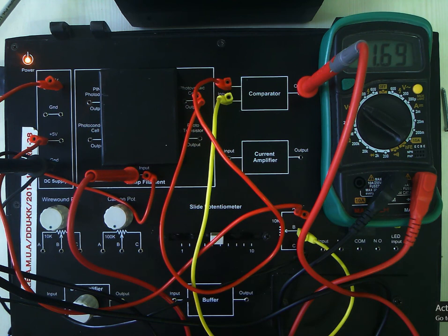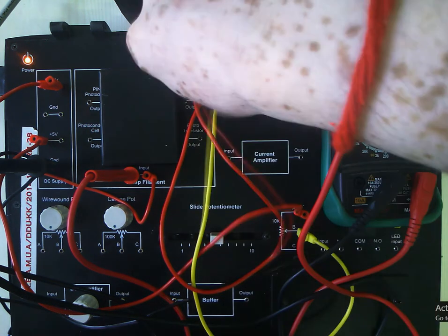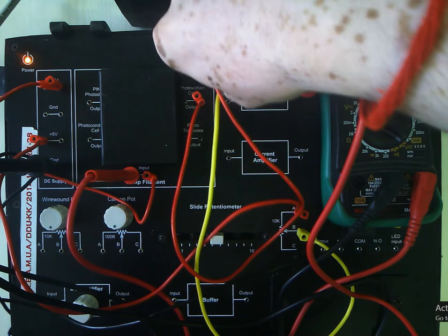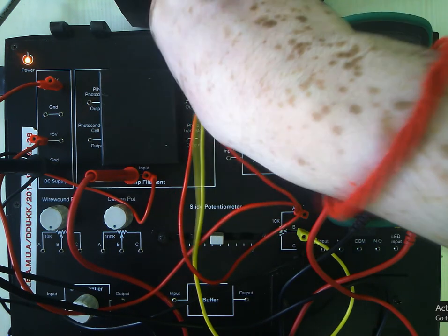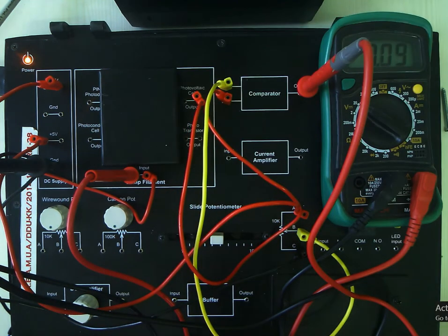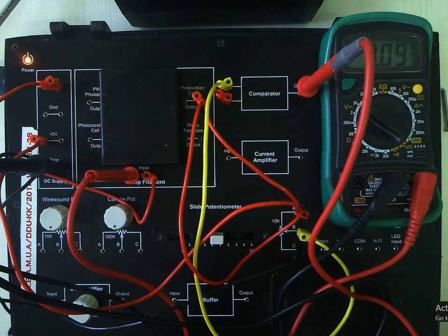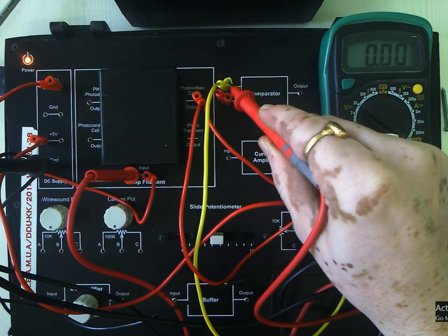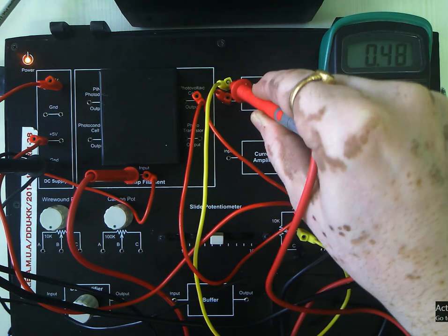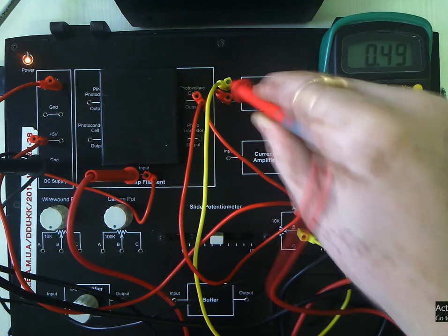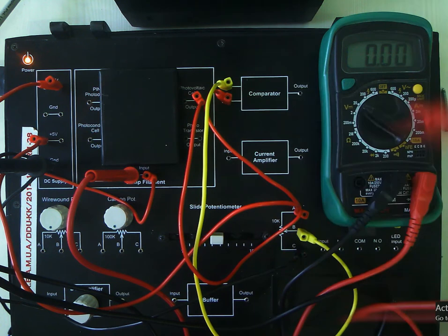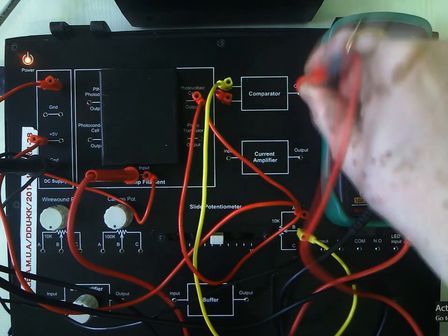Okay. What does that mean? That means that the reference signal has to be fed to pin number 1, or vice versa. There is no difference actually. Okay. Now you can find the reference signal is given at pin A, which is 0.5 volt, and voltage across the photovoltaic cell is 0. So the output of this comparator is 0.